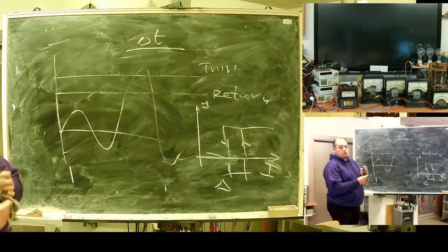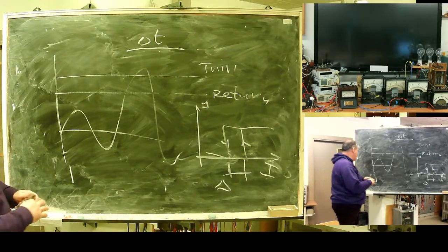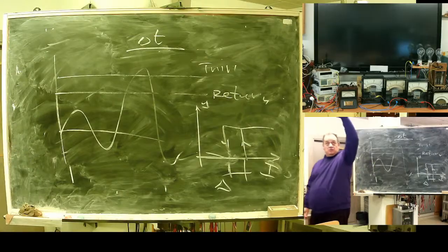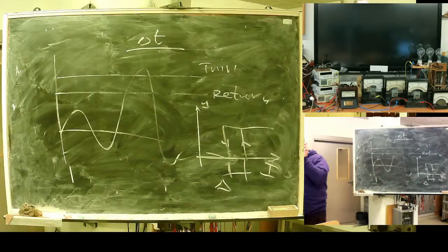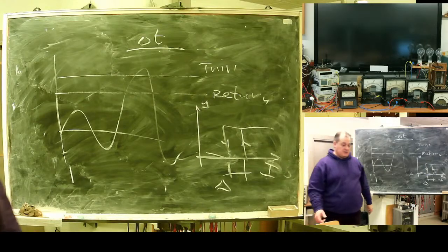Mostly I need to ensure selectivity between, let's say, bus protection and customer line protection. If there is a faulted customer, first the customer protection should trip, and only if unsuccessful, the bus protection will operate. To achieve this, I need time. I need to separate them with time gaps to ensure selectivity.